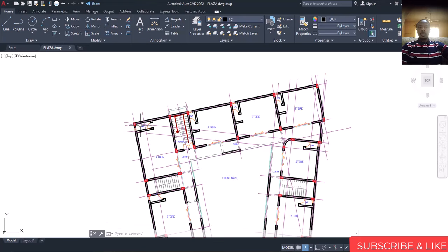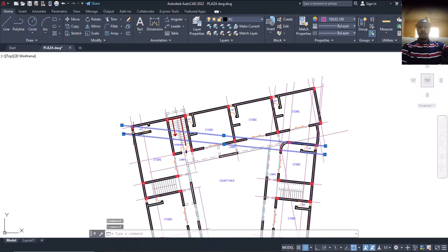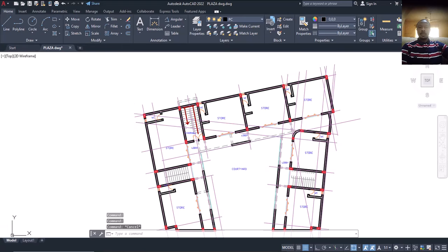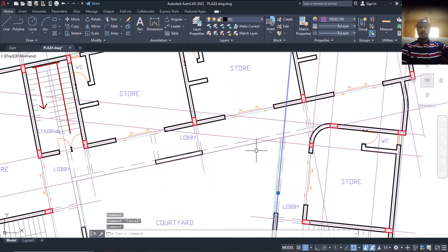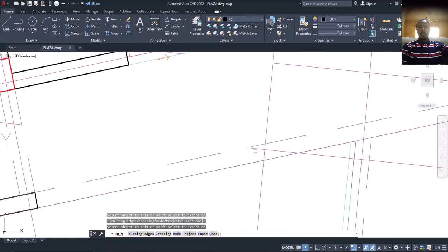So remain this one now. Likewise, if you look at this two and this two, they have no function here. Which means I need to trim off this particular one. So I'll come here, CP, enter, then from here the same 1500, enter, then escape, TR, enter, and trim off all these ones, and also this one, and then click on this and delete.